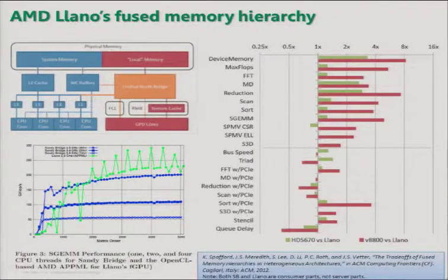And that's an x86 core, just like the AMD x86. You've got 4 of them, and then you've got a whole group of GPU cores, and it looks like a GPU for the most part. It's typically fewer cores than you would have on a discrete GPU. But the big key is you don't have that multi-microsecond bump to transfer data across the PCI Express bus. What we're trying to point out with this chart, and I don't want to belabor it, is the timing of our kernels not counting the data transfer cost, and the timing of the kernels counting the data transfer cost.